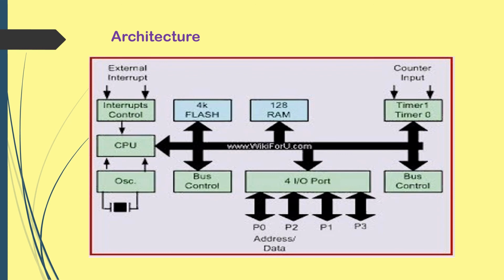Data bus and address bus. The data bus is used to transfer data; it is the electronic channel along which data travels. The purpose of the address bus is to transfer information but not the data. The information tells from where the data should be sent or received. The memory capacity of the address bus depends on the number of wires that transmit the signal, the address bits.